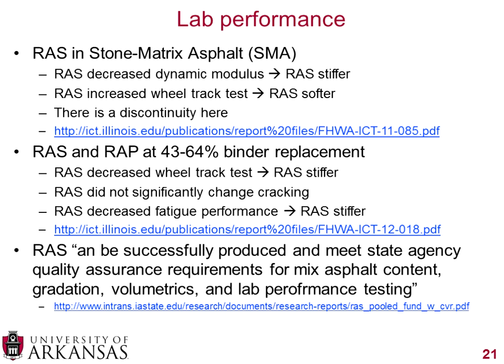It did not significantly change the cracking, and that's very important. One of the worries about using this stiffer material in a mixture is that it will be more susceptible to cracking, and this study did not find that. It did see a decrease in fatigue performance, which again indicates that the RAP was a stiffening agent. And you can find that link also in the chat box.